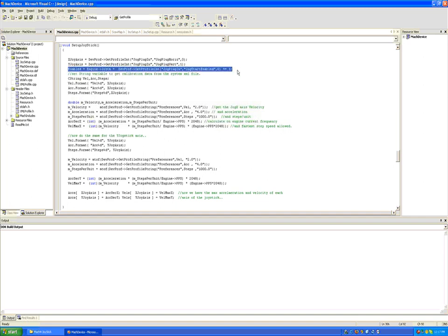With enabled, I am asking Mach3's XML file, has this person enabled this joystick plugin? If he hasn't, don't jog with it. If he has, remember it. And I remember it by writing those variables into the XML at some point during the run. During the setup of the joystick, I don't write anything, of course. I'm only interested in reading variables from the XML.